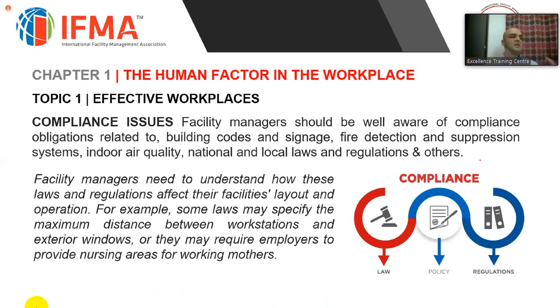It should have a certain number of doors. It should have a certain number of fire-rated doors. Depending on the area, it should have a certain number of sprinklers for the firefighting system. It should have a certain type of escape ladders, and so on. And that can change also depending on the nature of the business. If you are managing school facilities, for example, they have their own set of requirements, and these are compliance regulations mandated by law. In other countries, it's even more advanced than the minimum requirement here.